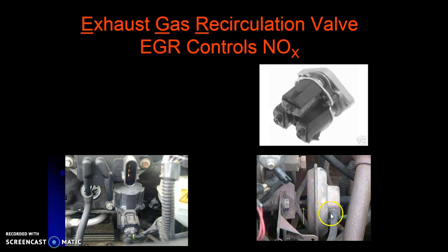But it has this little guy right here, will go to something very similar to this on the left, this little vacuum switch right here. This is being controlled by the computer to turn on vacuum to the EGR so it can move this plunger. And then the computer can tell the system's on with this guy right here. It's unplugged, but this DPFE, differential pressure feedback EGR, this system right here is going to have these two tubes that go across an orifice, and it's going to be able to tell whether or not EGR is flowing or not.